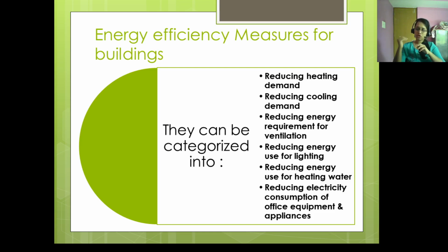Now the most economical house to build and heat is one with a simple square or rectangular plan. Complex shapes will increase the exposed surface area as well as the construction and energy cost. So we need to limit the exposed surface area of the building by avoiding these complex shapes, as this will increase the construction and the energy cost.